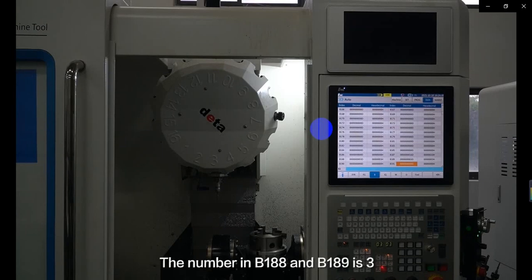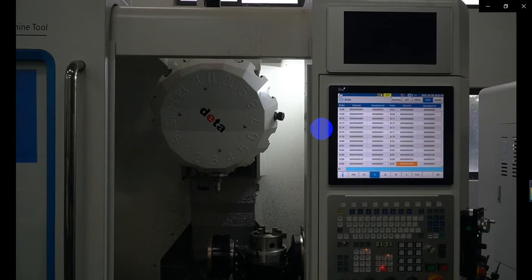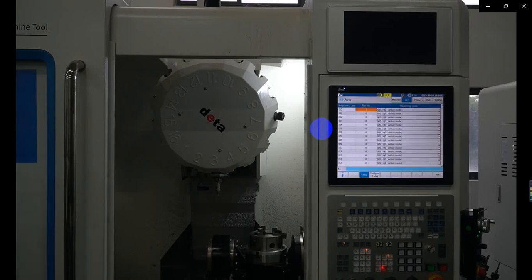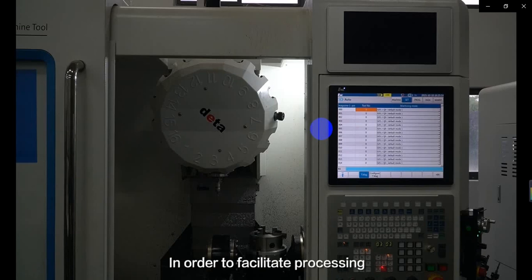The number in B188 and B189 is 3, which corresponds to the current spindle tool number and the tool pocket number. In this interface, we can see a total of 16 tools. In order to facilitate processing, we need to fill in each value from 1 to 16 to accurately set the tool magazine.